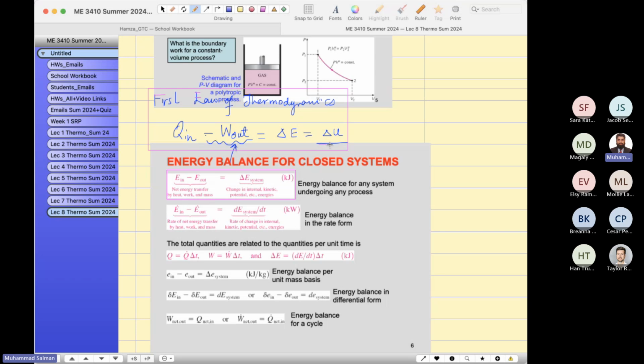If there is a closed system, you will just increase or decrease the internal energy. But if this is a moving system or an open system, then the velocity changes. In convergent nozzles, the velocity increases, so you have to consider the change in kinetic energy as well.